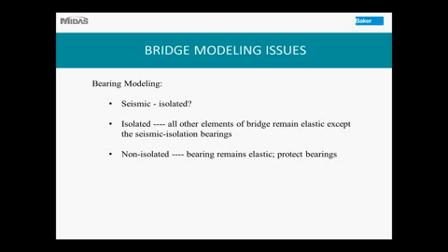And if you do not intend to design your bridge as seismic isolated, then the bearing should remain elastic, and that means you need to protect your bearing to make sure that the bearing does not fail before your ductile element fails. So you basically need to protect your bearings for a non-isolated bridge.